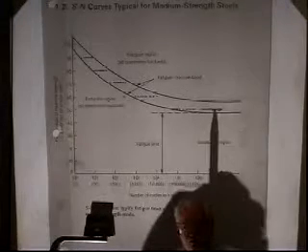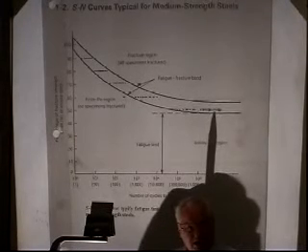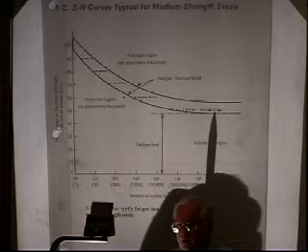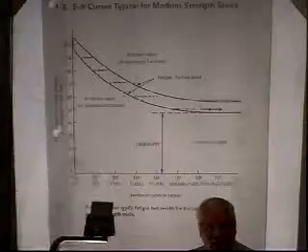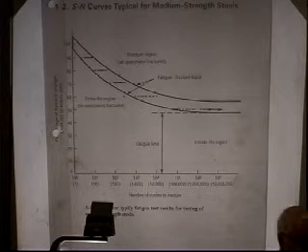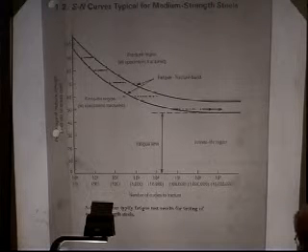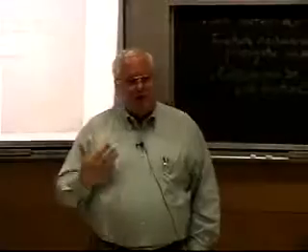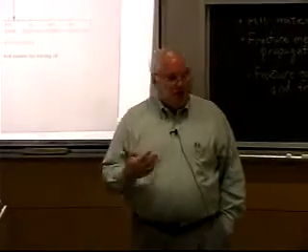The problem with most things is we try to design them to be out here in the elastic region. You don't want a part that's going to deform every time you bend it, every time you load it. So you design it out here, and sometimes they still fail. Well, why do they still fail when they're in the elastic region? Sometimes people talk about damage accumulation in the part.